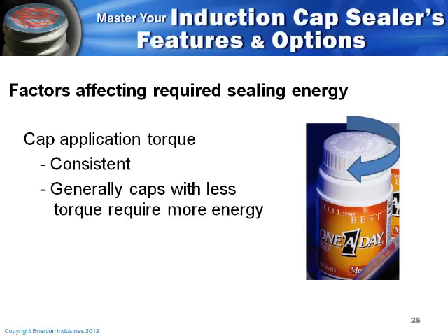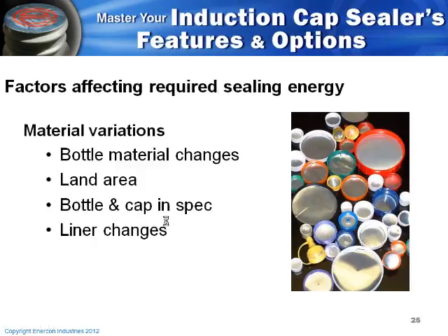The other rule that you can draw from this is, generally speaking, caps with less torque are going to require more energy than a cap that's more tightly torqued, given it's the same diameter closure.